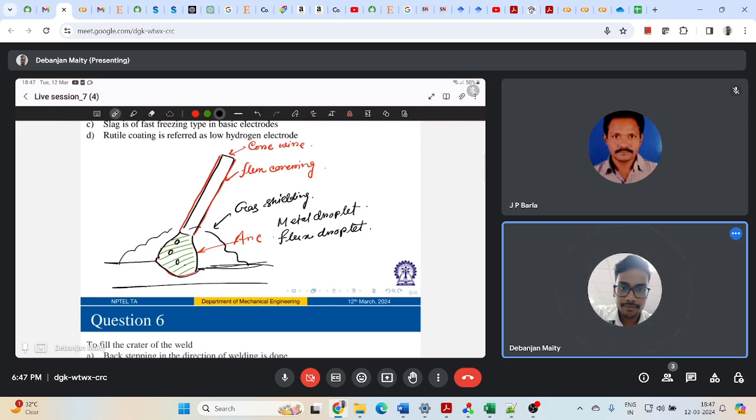It is the very fundamental part of shielded metal arc welding, as you know. So the core of this covered electrode, what we are calling the core wire, conducts my electric current to the arc and provides the filler metal for the joint, right? So your electrode can be consumable or non-consumable depending on it. You can use external filler wire, or you cannot.